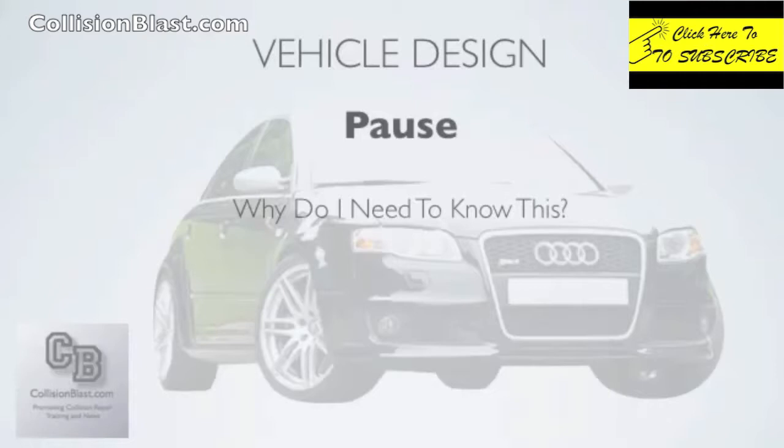If you don't really understand the concept, it's going to be hard to get it all in your mind, what happened in an accident and try to reverse that damage, because you've got to reverse whatever happened in the accident, the first in, last out. And we mentioned crush zones. You need to understand those and know where they're located, because if you're going to section something, you never want to section in a crush zone, and that's something you need to know. We'll talk about that in a minute. Some of the newer cars even have crush zones that you can't see, so it becomes that much more important to understand how vehicles are being made.